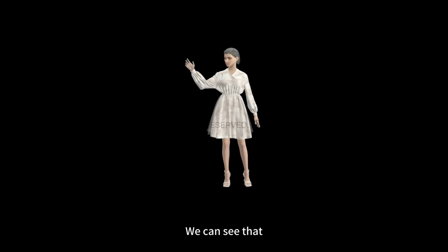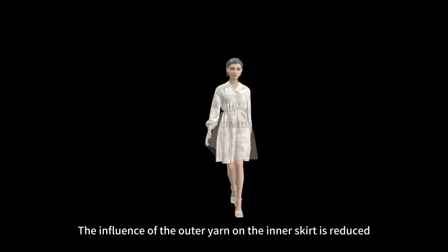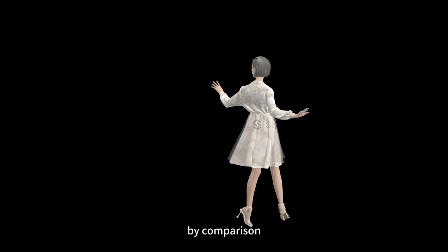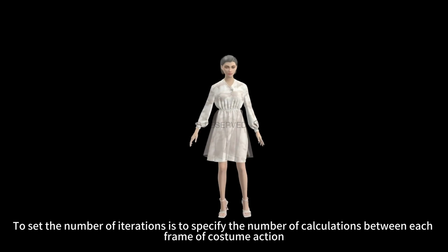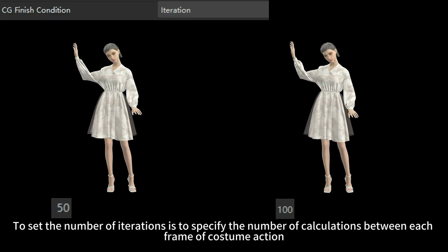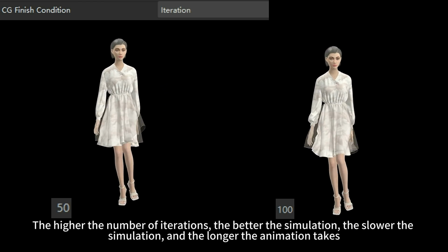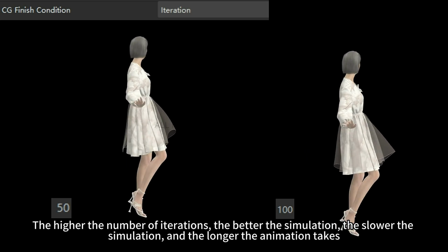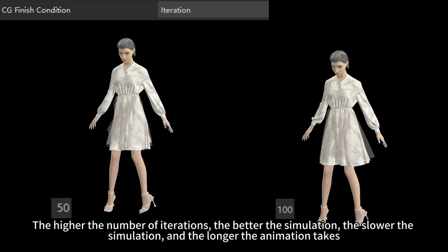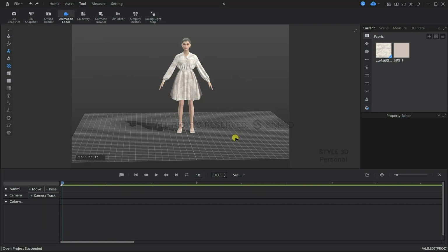We can see the simulation effect with 100 iterations. The influence of the outer yarn on the inner skirt is reduced. By comparison, setting the number of iterations specifies the number of calculations between each frame of costume action. The higher the number of iterations, the better the simulation, the slower the simulation, and the longer the animation takes. Next, let's take a look at the residual in the CG finish condition function.